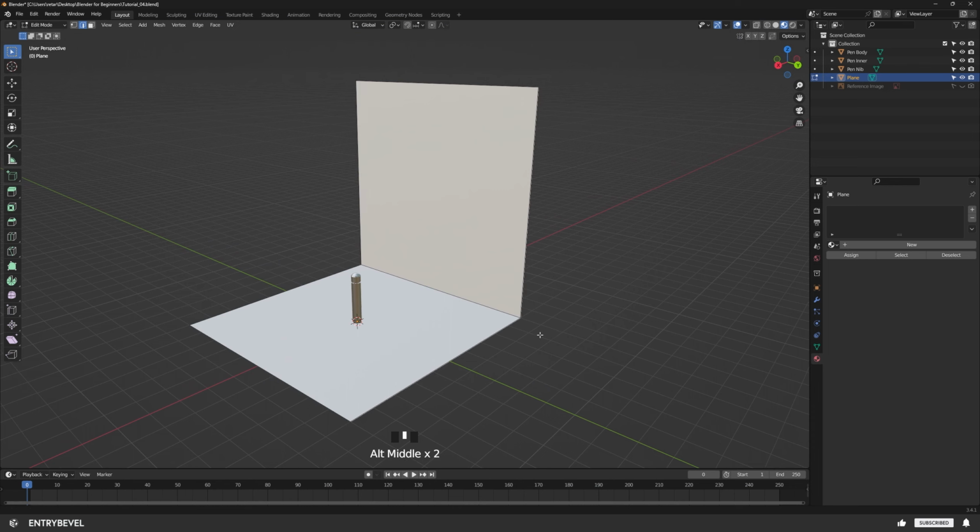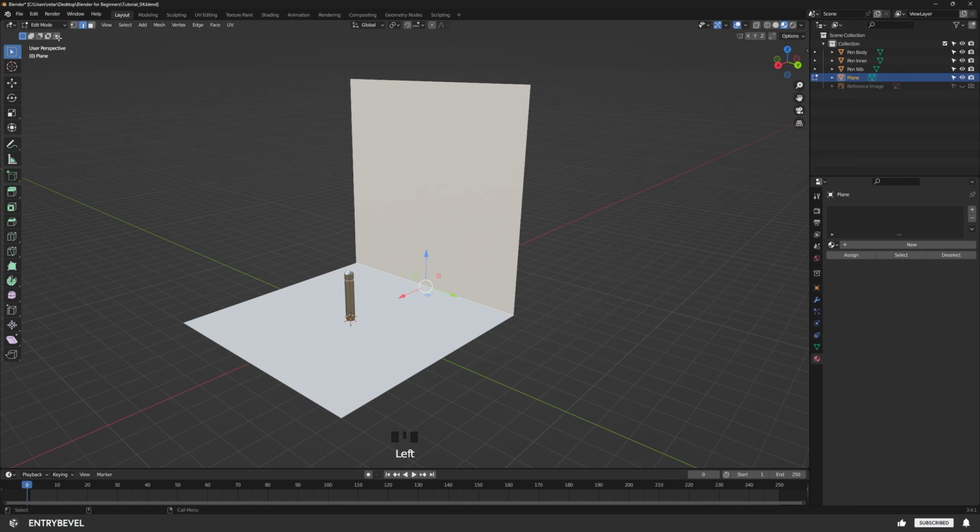It's actually quite simple. Select this edge, make sure you're in edit mode, edge, and press Ctrl B to bevel. As you can see, it's sort of making a curve, but it's very flat. We need to add more loops into this. So while you're still in this mode, scroll your mouse wheel. If I scroll once, it adds one loop. Scroll it again, again, again. Give it a nice tight curve.